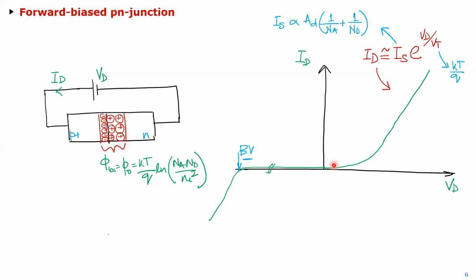And then in reverse bias, the current is almost zero till you get a voltage where it breaks down. Breaks down in the sense, there's a phenomenon called avalanche, which basically just destroys this junction, and then you almost get like a short. Okay. And these are some of the expressions for IS and the phi naught, which we just talked about, but that's something you can refer to. The books will not go deep into it.